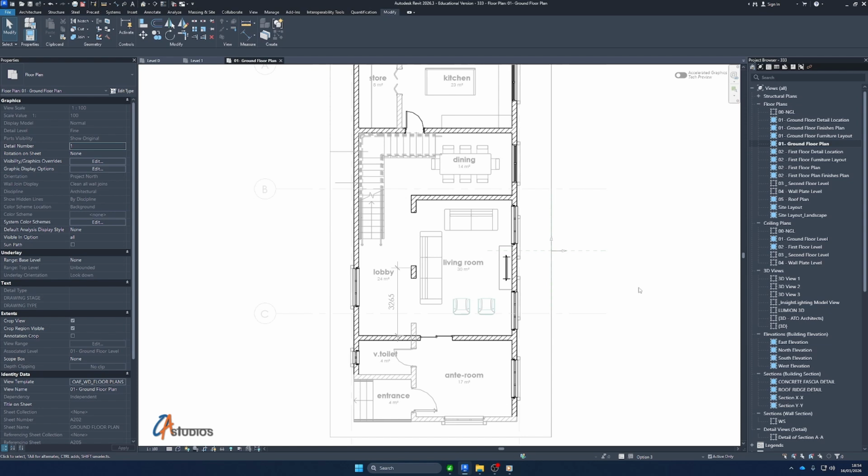Okay, now the strategy I'm going to take for this is, what I'm going to do first is to clean up one particular view and then duplicate the view before adding the design options to those particular views, so that I don't have to do cleaning up for 3 views altogether again.